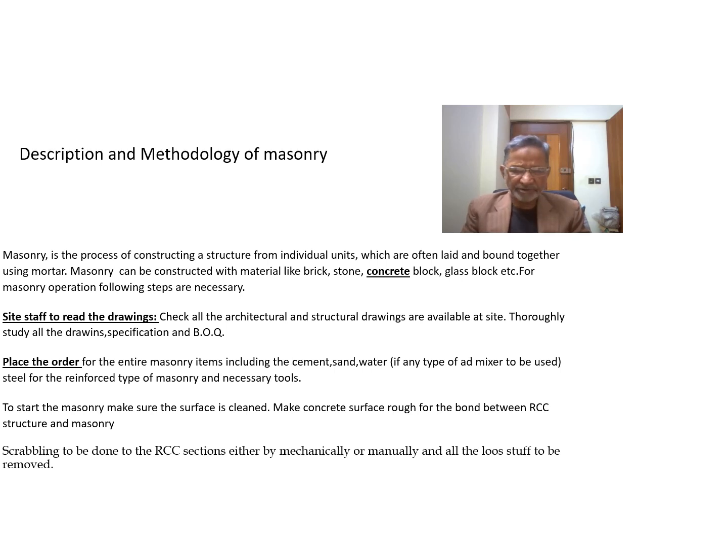Now we are going to start at the exact place of the masonry, so we have to take care of cleaning the entire surface and make it rough so that there is a bond between the RCC structure and the masonry. In this way we have to start the masonry work, taking the safety precautions also. All the safety is to be monitored and implemented at the construction projects.